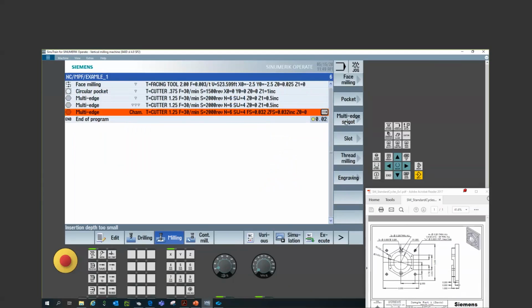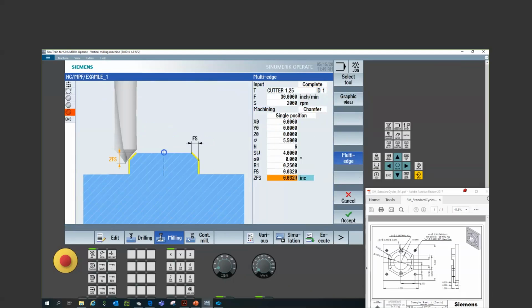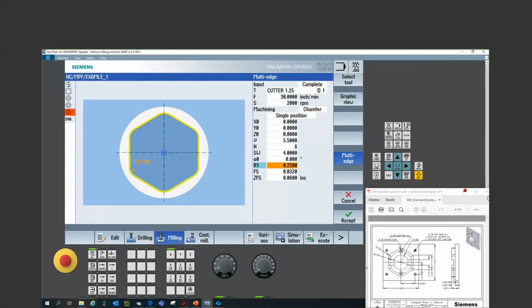And I believe the reason that it does that, and correct me if I'm wrong, Chris, is because of the angle of the tool, right? If it can't physically do that, the control does the math. So you have to have enough of a step down in order to get that to work. That's correct. Exactly correct. We have to have enough surface area or geometry on that tool to be able to machine it properly, for sure.